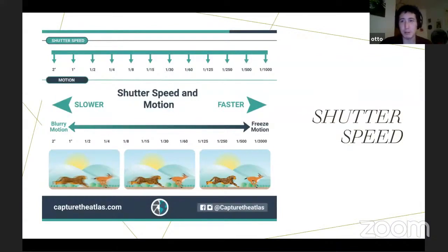So shutter speed is the simplest one to wrap one's head around. Basically, it's how much you're exposing your sensor to light. With faster shutter speeds, obviously, you're freezing motion and freezing the image more perfectly, and with slower shutter speeds, you're going to have blurs and motion blurs involved. So with photogrammetry, you want as crisp an image as possible, so you want to eliminate motion blur.